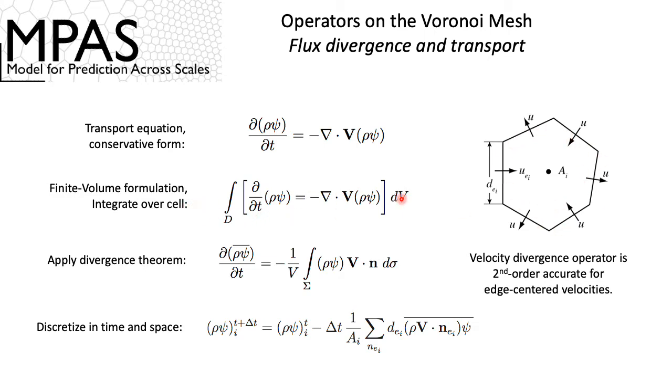So we perform an integral over that cell, and that gives us the equation, this third equation here, where the time rate of change of the average mass in the cell, and this over bar denotes a volume integral or an area integral in the 2D case over the cell, is equal to the integral over the cell here, which has been transformed using the divergence theorem to give you an integral of fluxes into and out of the cell over its boundaries,